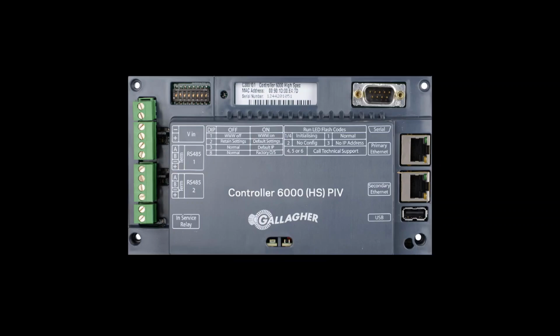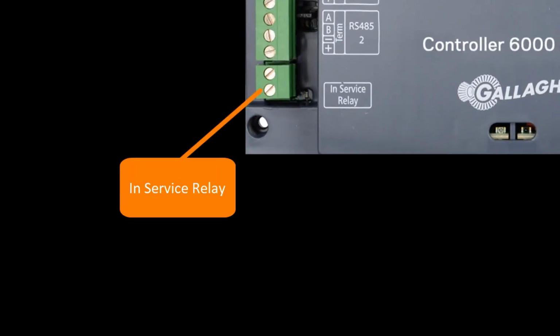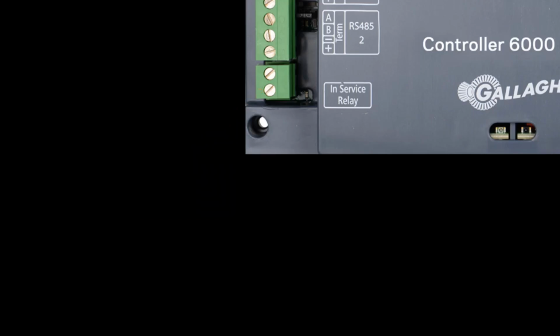Available on the 6000 high-spec controller, the contacts on the in-service relay close when the controller is powered up. Should power be removed, or in the event of equipment failure, the relay will open and be used to signal an external alarm.